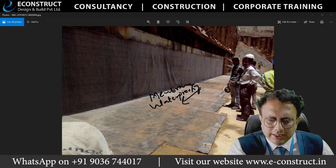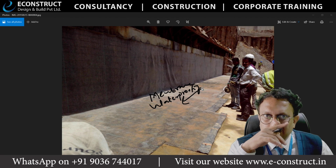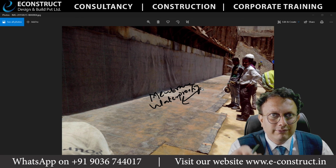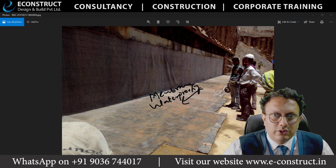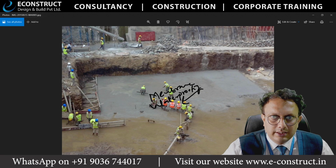Understood? Why is waterproofing required here? Because during the monsoon everything will be underwater. If the foundation is laid and the reinforcement is there, it will start corroding. Okay, so waterproofing is also important. Got it? Now the next one.